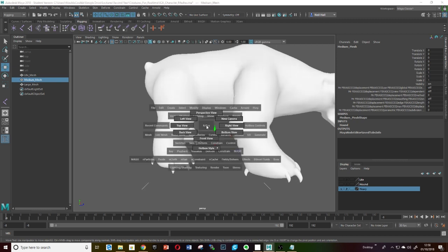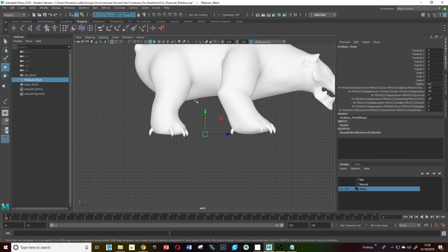If you look at where the legs are, just go in the left view perhaps. Now, the chances are in his legs you're going to have a bone here, a bone here, and a bone here. So the bending here is going to be around this axis. So really when you start adding all your joints, you want to try and add them on the plane where the bending or the rotation is going to occur. The neck, it doesn't really matter, but it's always useful just to keep the same side as the spine. Any kind of extra bones you might need, we can add in at a later point.